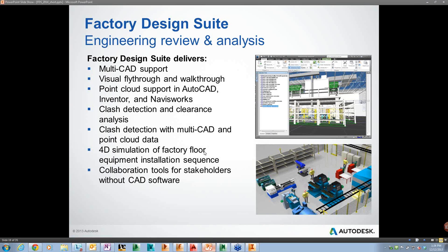As you mentioned, modeling in 3D gets very, very detail-oriented. I have all the nuts and bolts for each machine, and I don't need that in a factory representation, so I can simplify that out. There are some workflows inside of Inventor to do that. But as I start building 100,000 square foot facilities, that's going to be a lot of 3D data. So what we can do is leverage a tool like Navisworks to aggregate those and make those files more manageable.